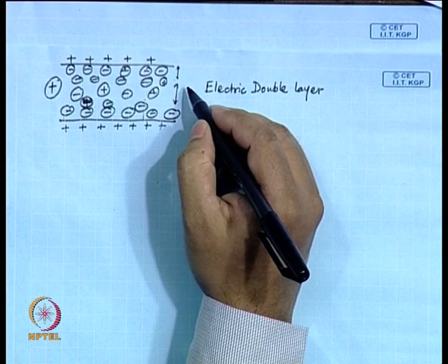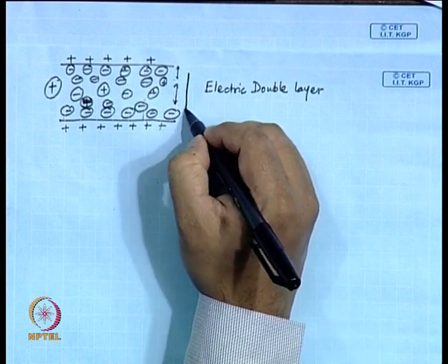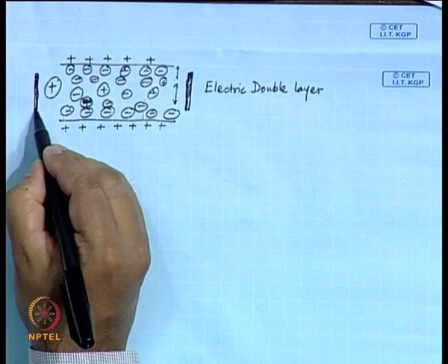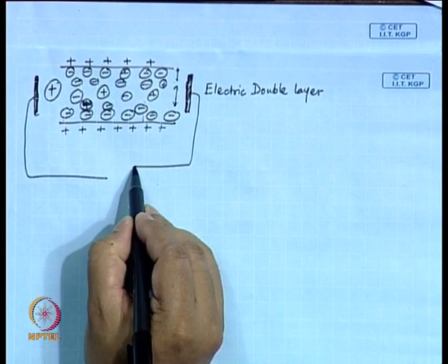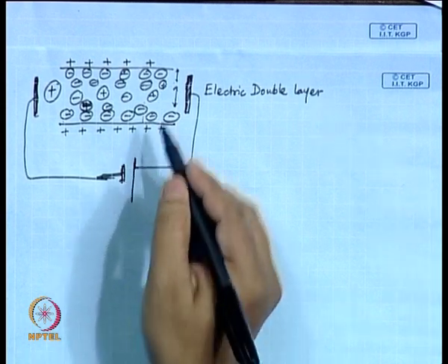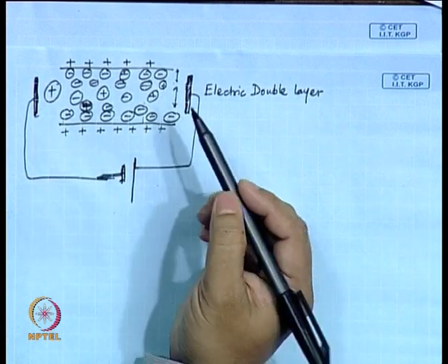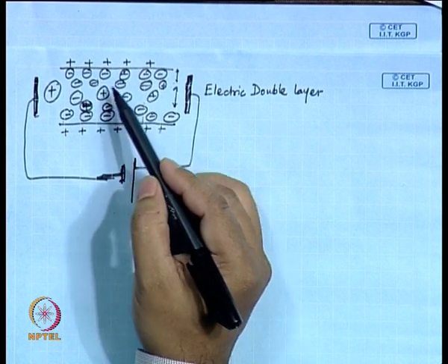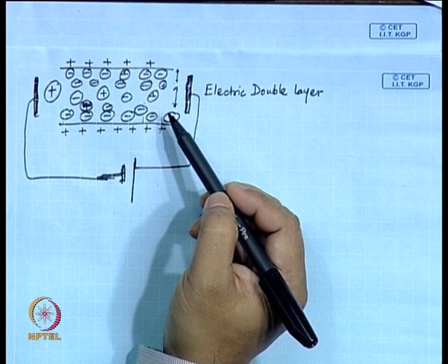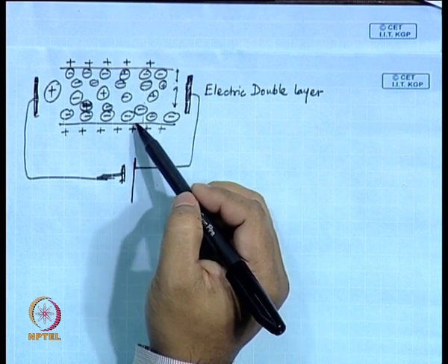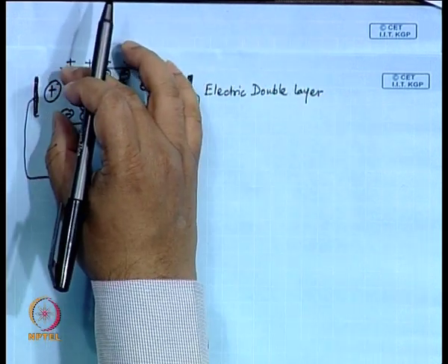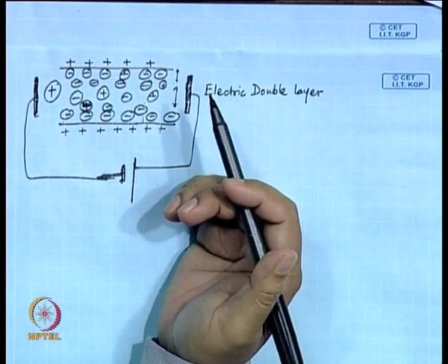Now, suppose you put an electrode here and another electrode here, one acting as an anode and the other as a cathode. What will happen is that these negative charges, from the diffuse layer, which are mobile and free to move, not sitting next to the wall held permanently, would be pulled towards this direction. While these ions are moving from one direction to the other, this generates a drag force.